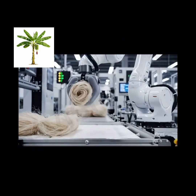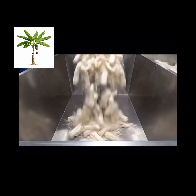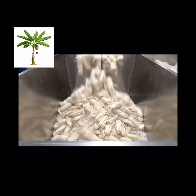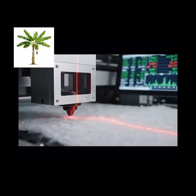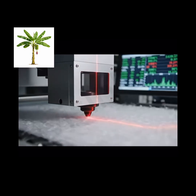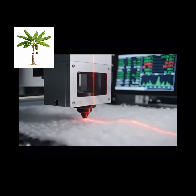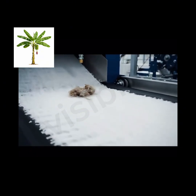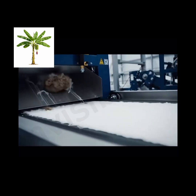From here, the fiber goes through carding. Carding machines align fibers parallel to each other and remove remaining impurities. This produces a loose rope-like structure known as a sliver. Multiple slivers are combined and drawn. Now, drawing equalizes thickness and improves fiber alignment. Sensors continually monitor mass variations and adjust drafting ratios automatically.